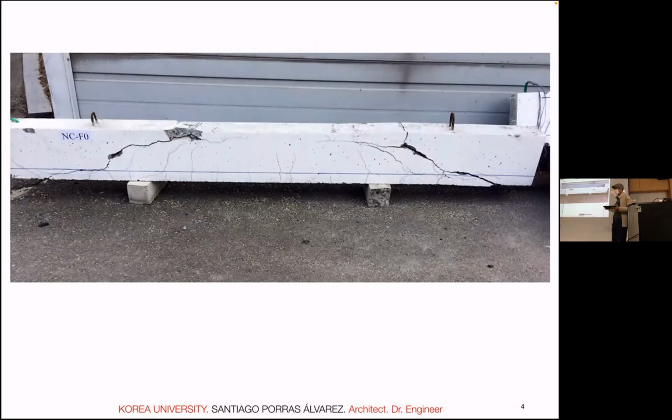And this is obviously one case in which the shear crack happens at the end, near the support. That means probably the load is continuous and the most stress is at the support, where most of you drew it. With one load at one point, the shear is the same on all sides, so the crack may appear anywhere in the beam, right?